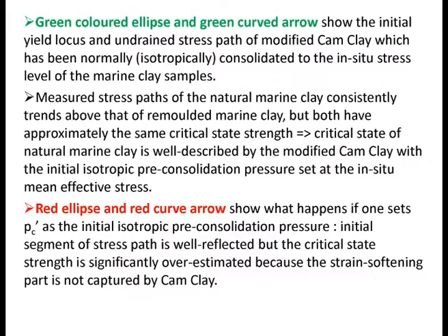The green arrow and the red arrow I already mentioned to you. The green arrow is to say use the original friction angle but ignore the over consolidation ratio. The red arrow says use everything. Use the over consolidation ratio, use the original angle of friction, but it is unconservative. So it's not a recommended course of action.